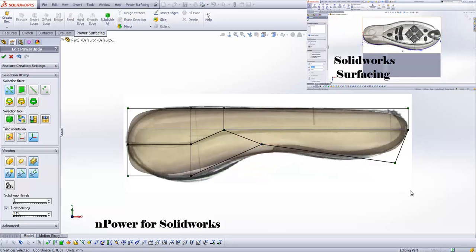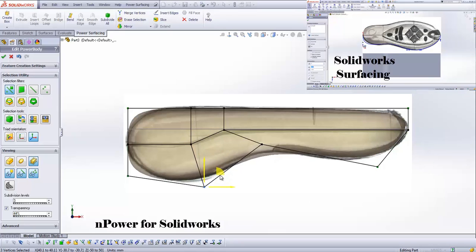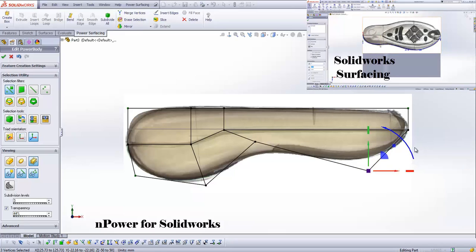I'm just getting this side profile set, and then in just a moment we'll flip over and take a look at our other profile. As I'm stretching these along, I'm matching the underlying shape that's been created in these sketches by the industrial designer. In the top right I am doing the same, but I'm having to set up all these sketches with splines and really get things nailed down.